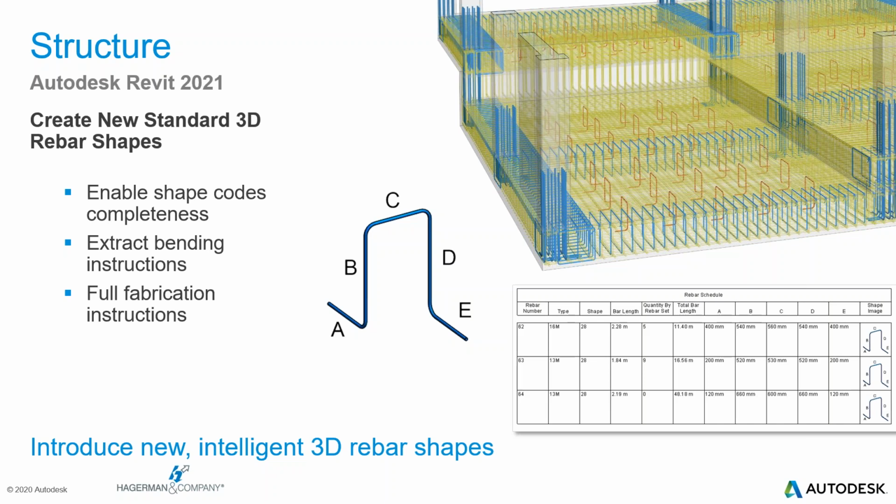In Revit 2021, you can add an end treatment to the end of any rebar without the need for a rebar coupler. Simply select any rebar and change the end treatment at start or end to any of the values defined in a project. This new feature provides structural engineers and detailers with greater control over reinforcement and treatments.